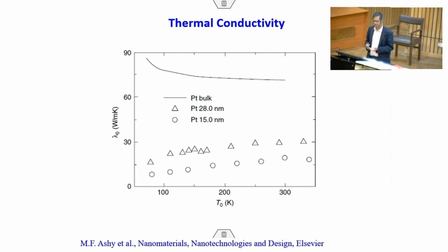Or you can have thin films composed of a collection of nanostructure units. These nanostructured thin film materials can be subdivided into nanocrystalline materials or nanoporous materials. So the moment you have multi-layer thin films, each layer's grain structure can be nanoscale or micron scale. Both are possible. The fact that each layer is of nanometric thickness makes it a nanomaterial. You can also have nanometric pores in the layers. So you have these three or four different types of situations.